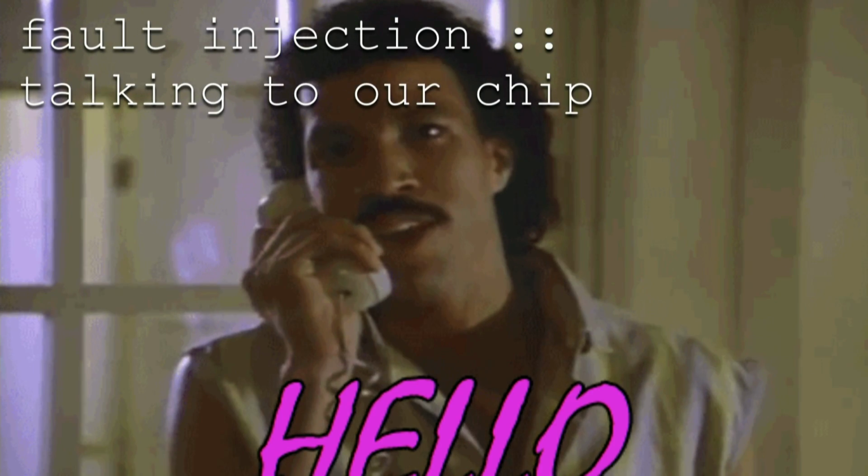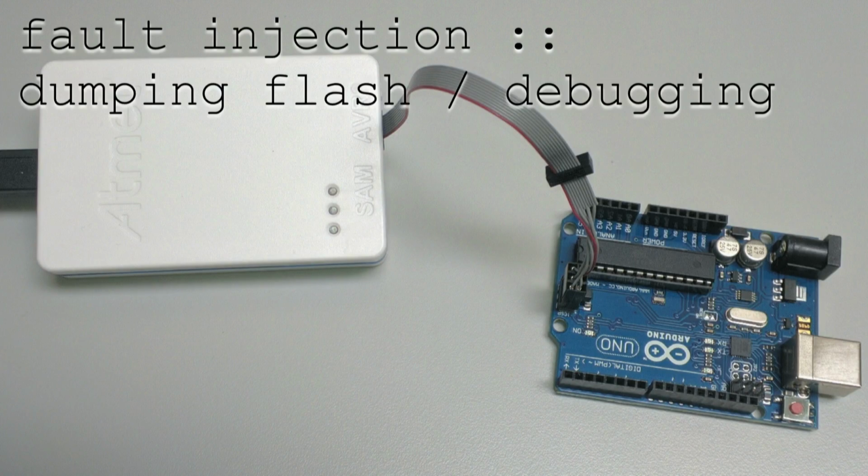To actually extract a password, we can use something like a debugger. With an Uno, you can get something like the Atmel ICE, you can use a JTAG or a Segger or a JLink, things like that, to basically communicate with the chip. The chip has a boot ROM, it has debug wire, and it has these features that allow you to actually access the flash inside and extract that.